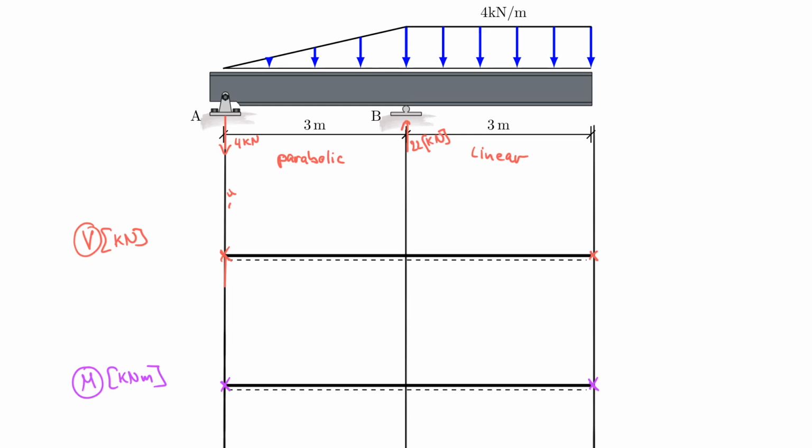Now where that value is, I don't know yet for sure. I will calculate that in a second, but I know that at this point I will actually have a jump. So let's pretend that I have this here, and then I must have a jump that follows my arrow of 22 up. So now the question is, am I less than 22 here? Do I go through 0 or not? There are two ways I can think about this. One way is I can relate it to the moment diagram, because I know that the bending moment must be maximum over this location here because I'm pulling down. I make the beam frown here, and so therefore it has to pull down.